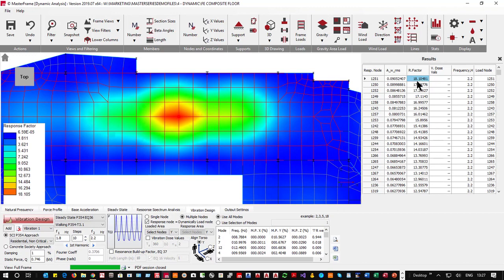It is quite significant, and we would really need to go back and put in different thickness of material or different section sizes to try and get these response factors down. But we're going to keep going and look at what this can tell you, because this doesn't design, this just tells you what your values are, how close you are, how significant it is. And we can see that we're getting this as a factor of this. We can see that this mass participation is working here.